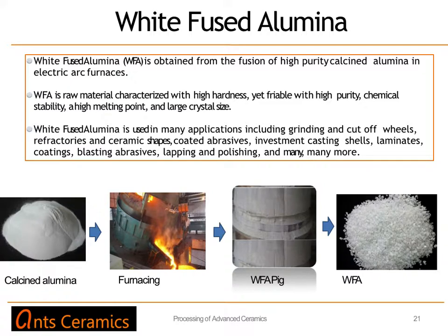But white fused alumina applications are different from tabular alumina because tabular aluminas are not so friable, and those are generally sintered aluminas. These are melted, quenched and crushed aluminas. So these have much sharper edges and corners, and friability is much higher. So in grinding applications, generally white fused alumina is much more preferable than tabular alumina.